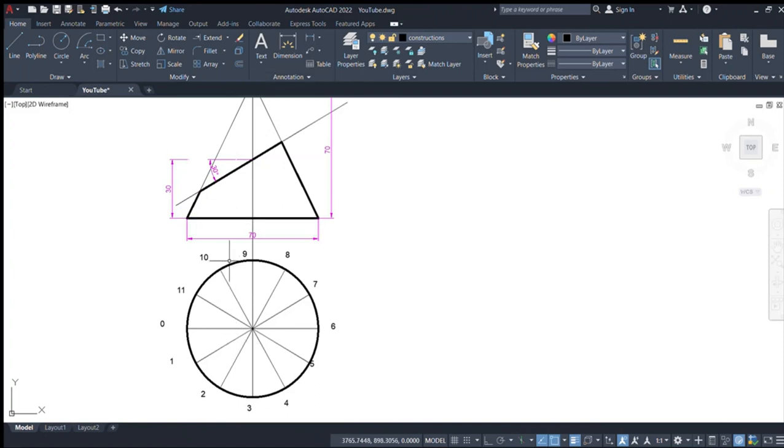cone, if you look at the cone from the top, the plan will be circular, but now because it's cut at this point, it will have a certain feature here. So let's start. The first thing, draw the circle of the same diameter as given, and subdivide that circle into 12 parts. Once you are done subdividing it, now project these lines vertically. So let's have generators from each of these points to our plan.